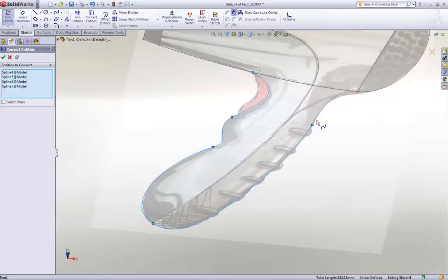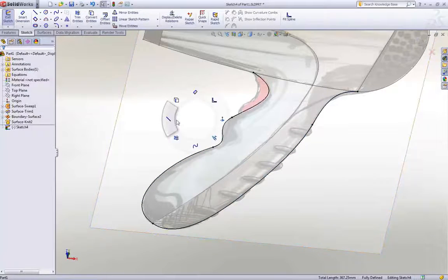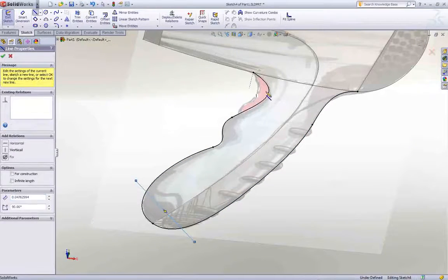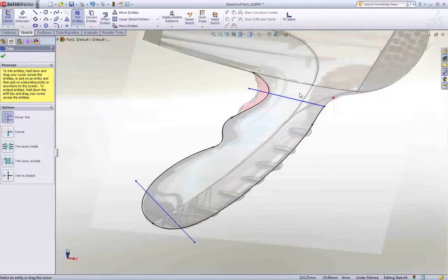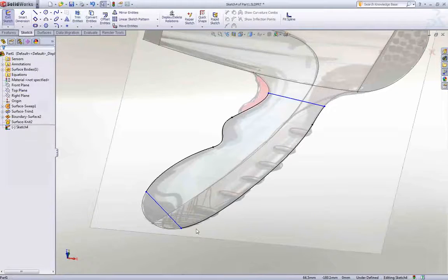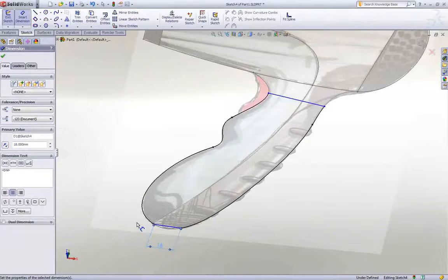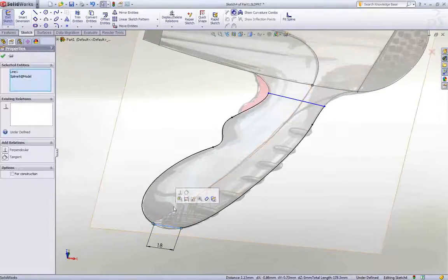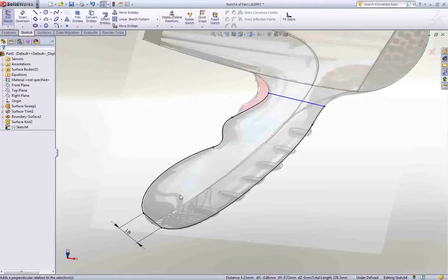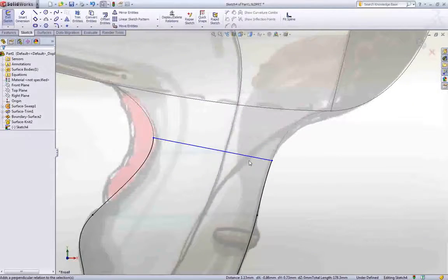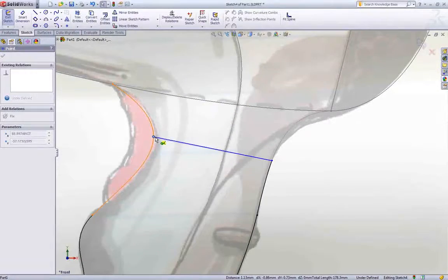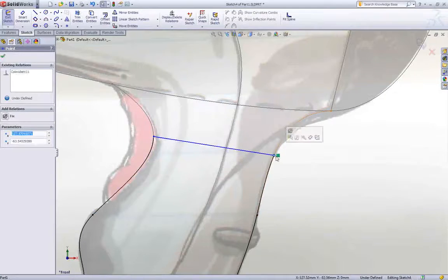Building the network of curves required to create the surface for the handle would be tricky without the level of control offered by SOLIDWORKS. Here we are again, using the imported curves as a foundation, copying and trimming them to the correct shape. Concept design and detail design quite often conflict. Using a tool that is built for both enables you to consider manufacturing details early on, like the hole size and location for the power cord, so design changes are reduced further down the line.